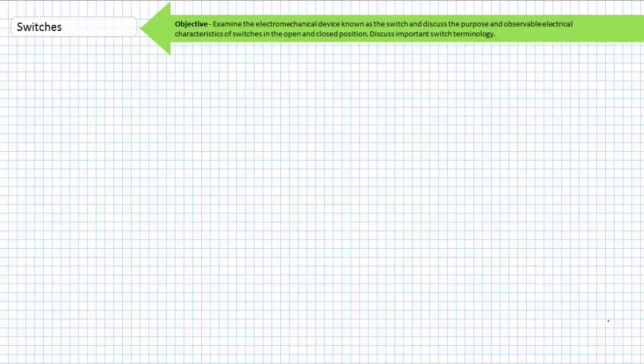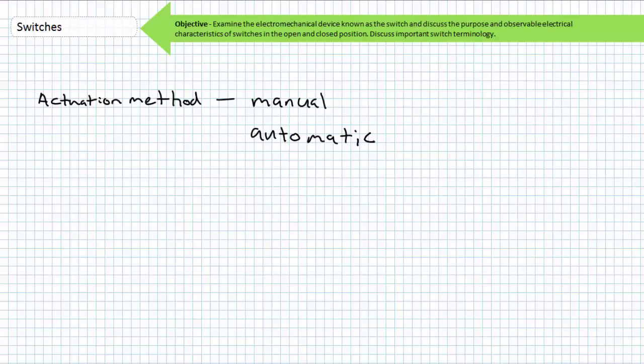Moving on, let's discuss 3 important distinctions between switches: that of their actuation method, natural deactivated state, and activation period. Actuation method is generally divided between manual and automatic means. A manually actuated switch might be a button, a lever, or a handle, basically something you hit with your hands or maybe your feet if you're sufficiently dexterous. A stop, start, go fast, lift off, or self-destruct button might be examples of manually actuated switches.